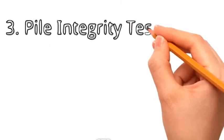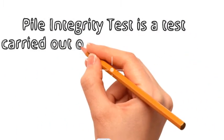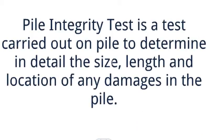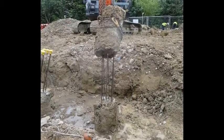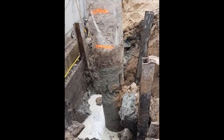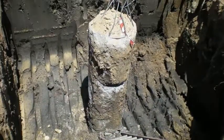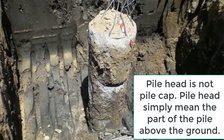Number 3 is the pile integrity test. Pile integrity test is a test carried out on pile to determine in detail the size, length, and location of any damages in the pile. When casting the pile, there may be some areas of the pile that are not covered by concrete. There may be void within the pile during installation. We can have defects like necking, cracking, or bulging that may be within the pile, which we cannot physically see because the pile is installed inside the ground. Only the pile head will be seen at the top.